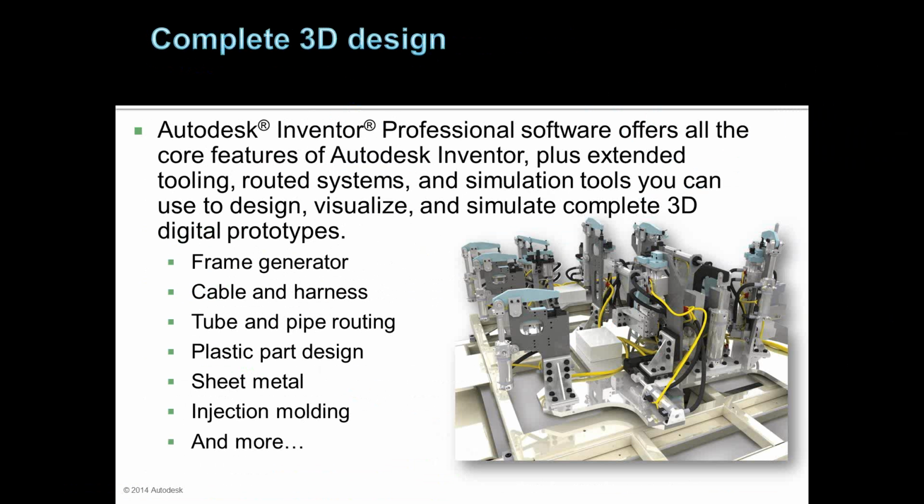The frame members in Inventor are more or less intended for small structure, not talking like a house or an addition onto an office building, but we're talking something like the framing for a large piece of CNC equipment, or maybe framing for some kind of overhead trolley system, truss work, things like that. Can you go ahead and design framing for a building? Yeah, I mean, it's not going to have a limitation on it that you can, but it's not the ideal tool to do that with. So with the frame generator, you're sticking with smaller scale structures.